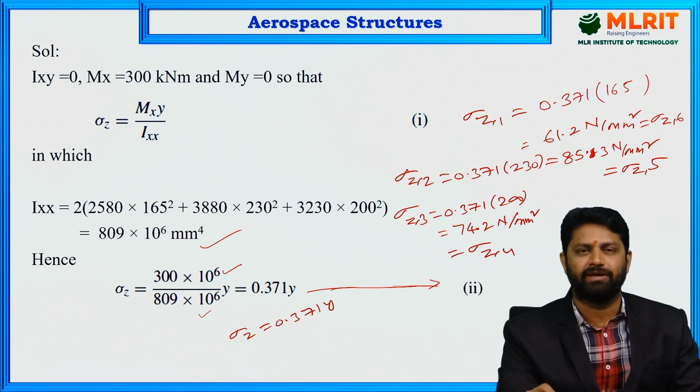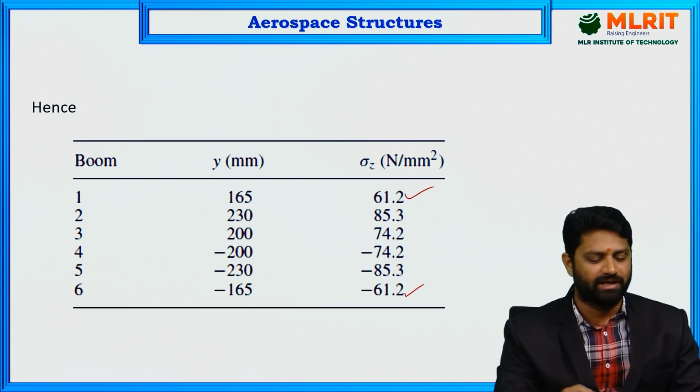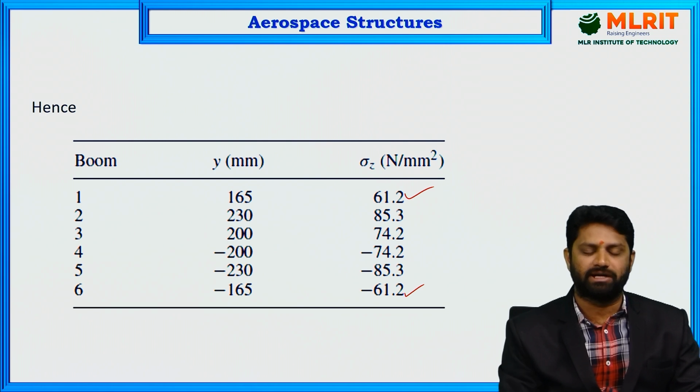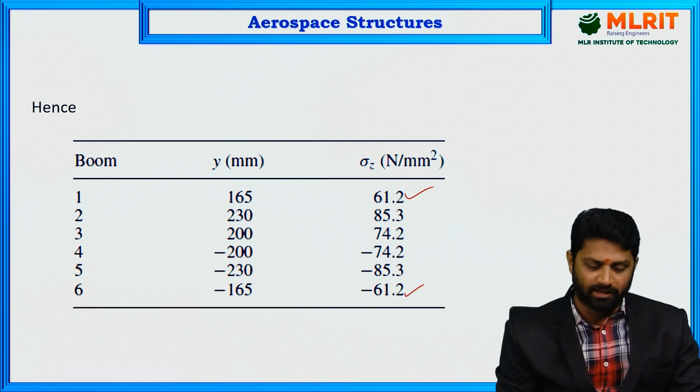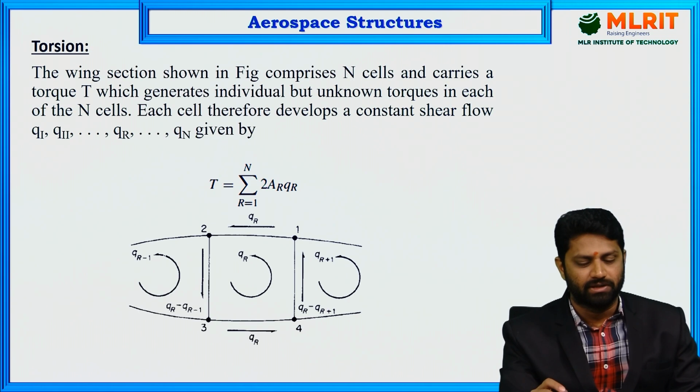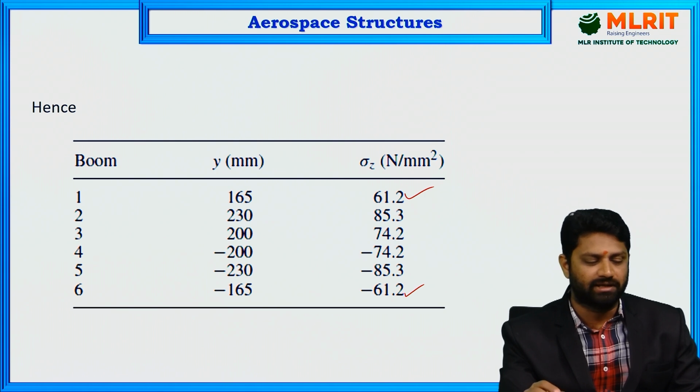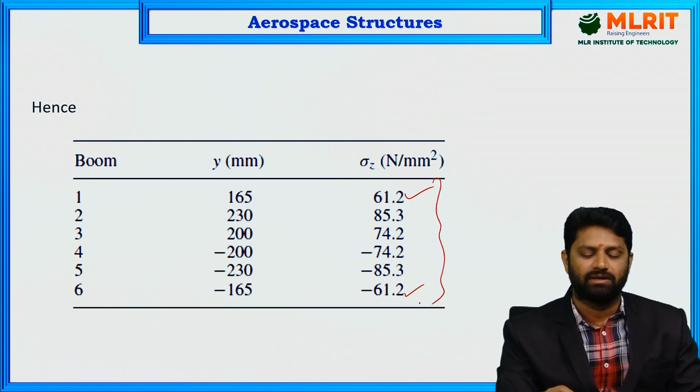In this way you can calculate all the boom areas and the respective direct stresses in all 6 booms. Okay, so this is how we calculate the boom areas and the respective stresses in all the booms.